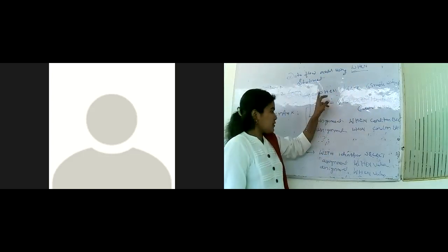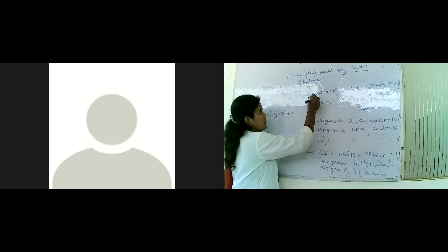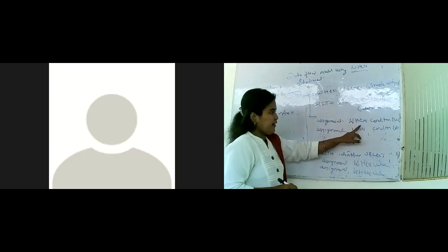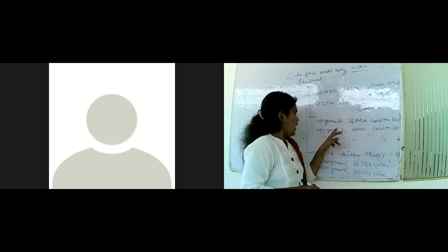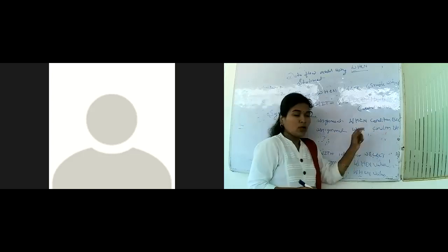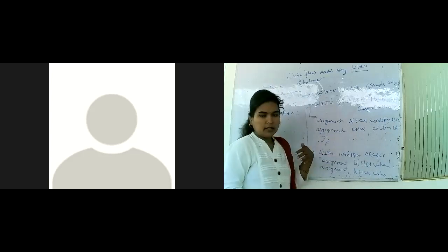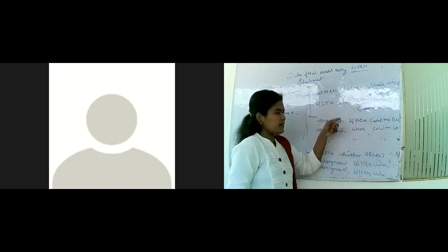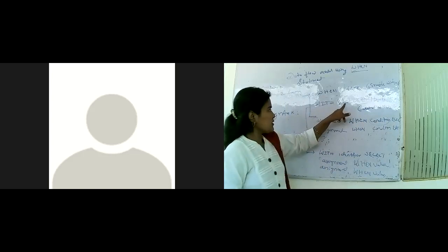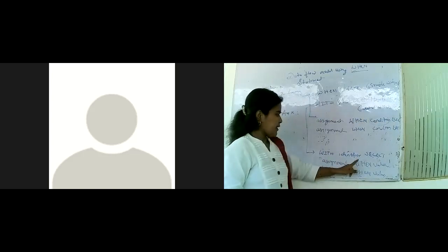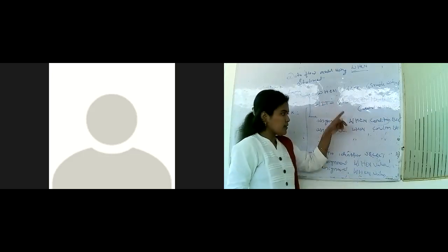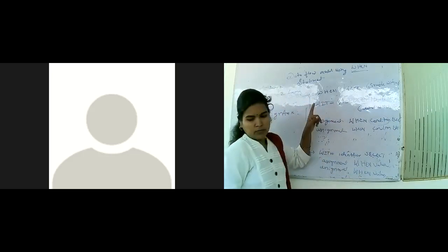So this is the syntax for this one: assignment when condition else. What is the condition? We have some conditions. If I give an example, then you will understand this syntax. Next is with select when: with identifier select assignment when value, assignment when value. This is the syntax for these two forms.